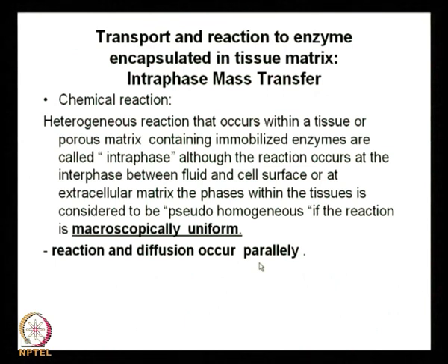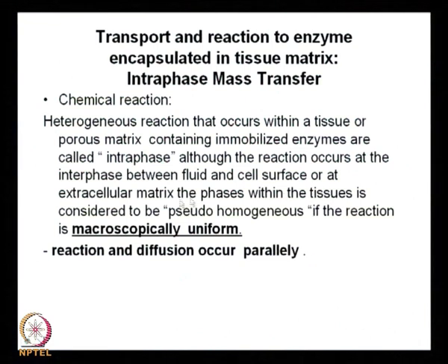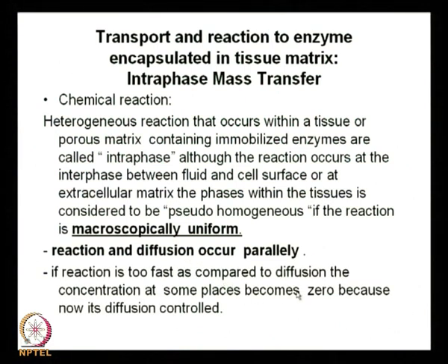Okay. Is that clear? In the real model, in real life, diffusion and reaction are not occurring simultaneously. In the heterogeneous model, diffusion and reaction are not occurring simultaneously, remember. So, first diffusion followed by reaction, but in the pseudo homogeneous model, diffusion and reaction are assumed to occur parallelly.